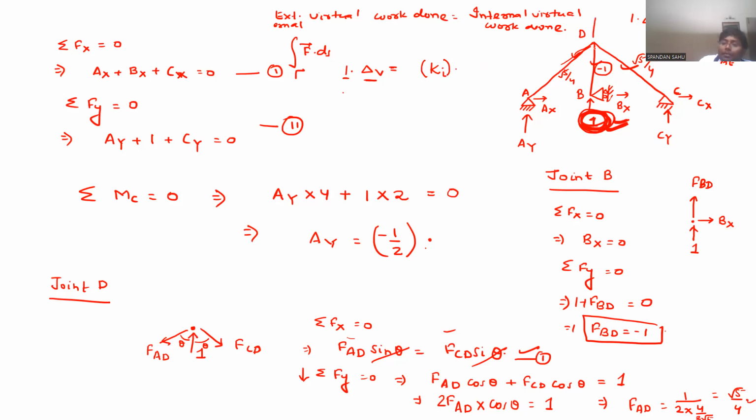Now see, this one was virtual, so the forces coming due to it are also virtual, but this one was real. So corresponding to this, some real deflections will be developed due to the external load, that will be termed as PL by AE. Because you know, for axial members, when you give a load P, the deflection delta will be PL by AE. So PL by AE of i, and i will be summation over all those members, i equal to 1 to, in this case for example, 3. Now you got it. So from this, you will calculate directly the delta V value.